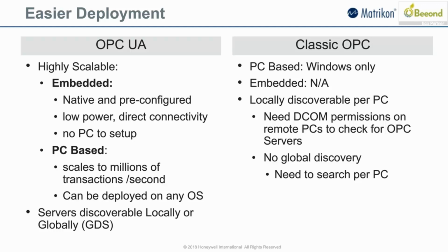So if you have OPC infrastructure in place, that does not mean it's time to rip it all out because it's older. It just means that going forward, it might be a good idea to start a phased adoption, blending in the new technology while you continue to get value out of your existing technology, and maybe propping it up a little given some of the new utilities that are out there. Okay, so Classic OPC obviously just runs on Windows, you have to find the different servers per PC, and you have to have permissions to talk to them.